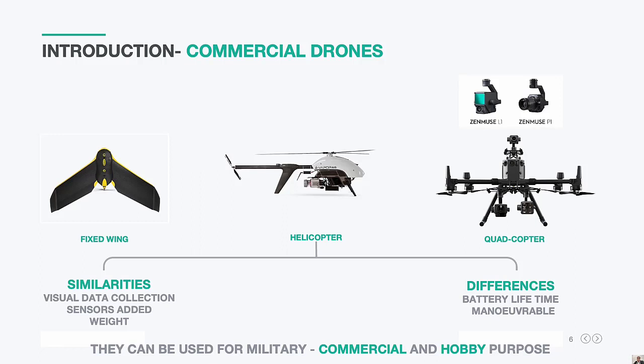And then quadcopter drones are mostly going to be used to make surveys of short areas of construction sites and focus more on inspection and accuracy. What things do we actually want to measure? Do we want to measure features in a concrete slab, or do we want to measure the topography of the surface of a specific area where we want to build a building? There are plenty of sensors that can help to inspect bridges on the upside and downside, on both sides. Then we can make a reconstruction with that.